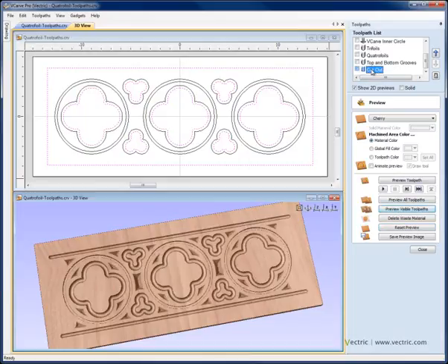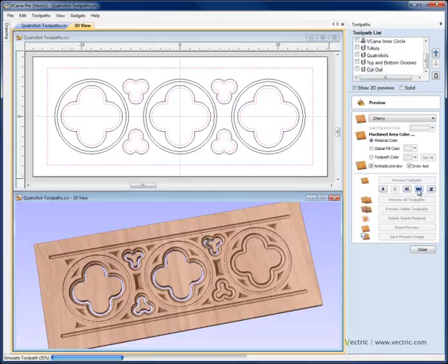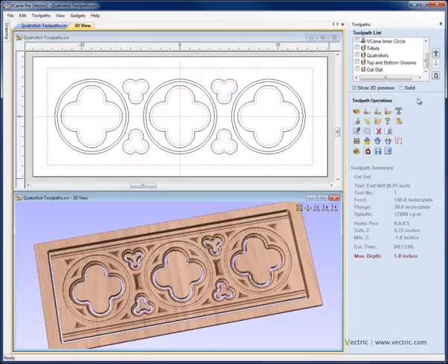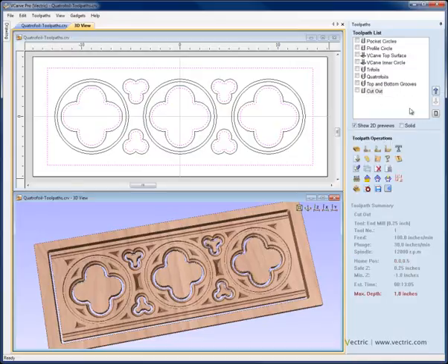So it's going to preview each of those in turn. And now if I want to look at this last cutout, I'll switch on the Animate preview and go to the run to retract. And this time we can see it showing us the area it's cutting out because I have the Animate checked. So I can see that it's cutting out the inside shapes first before it goes ahead and cuts out the outside shape. So if we close this now, we can see we've created our toolpaths. We may want to drag our menu down because we've got quite a few toolpaths in here now.